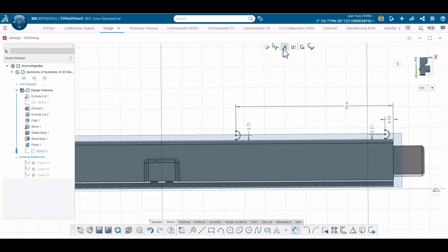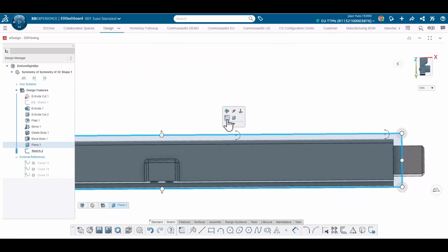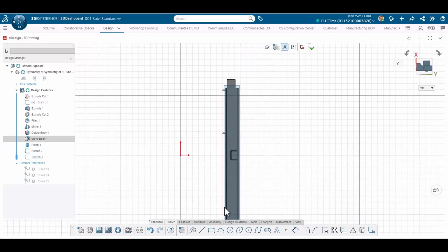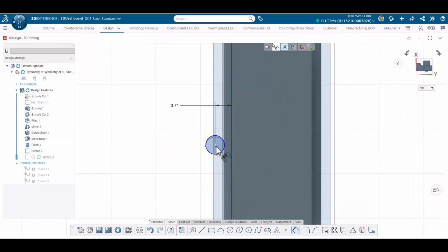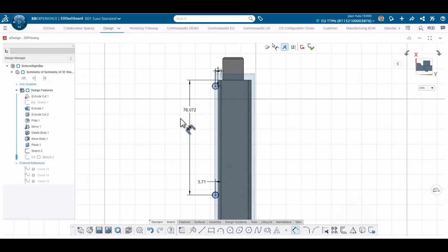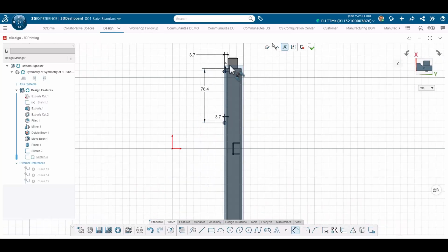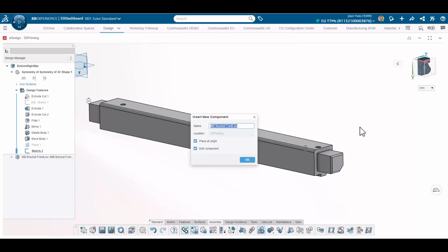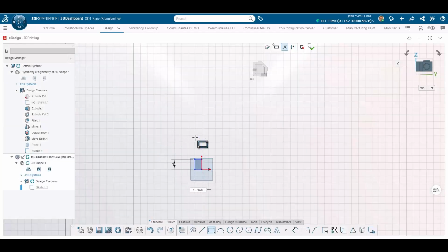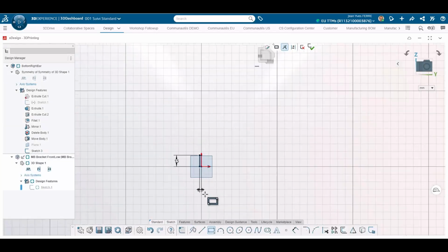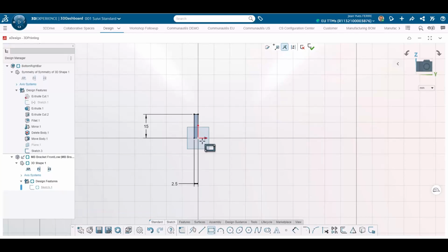This one is a mirror part of the top one, so I will leverage holes already made. I position sketch so they don't depend on the motherboard anymore. Remember, the less useless external references, the less risks for rebuild loops. Here the motherboard won't move, so I rather add dimensions. Then I can start creating mounting posts. They will be simple but strong enough to maintain the full computer assembly.